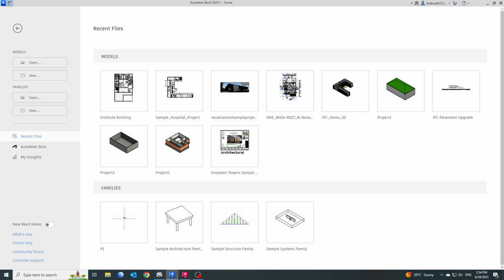So now in this example we will take a case scenario in which we are going to start a project. We haven't started modeling any building element yet. Before that, we will bring in an AutoCAD file, that is a DWG file, which already has coordinates assigned to it. This drawing will act as a kind of parcel drawing for a building.